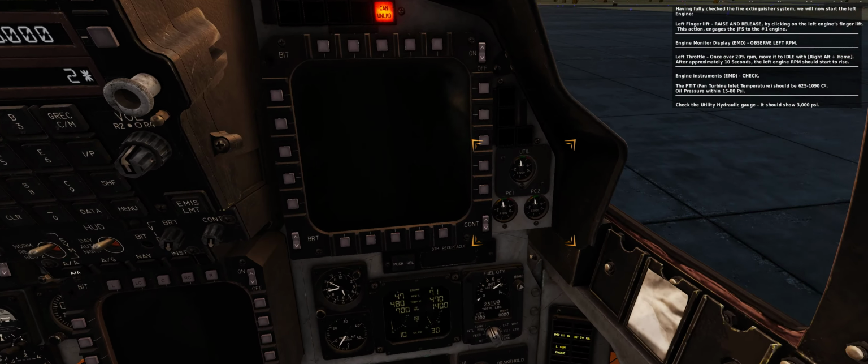On the left multi-purpose display, MPD, push the highlighted button, AA radar, to display the air-to-air radar screen. While the radar is on standby, the STBY status will appear on the lower right corner of the display. Other indications are off, EMER, and blank when the radar is on. Press spacebar to continue. Nav FLIR power switch, set to standby.